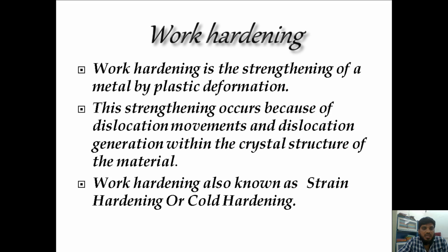I can tell you an example. If you are stretching a material and you leave the material after stretching, you have given a plastic deformation to the material. The important thing is that it is not applicable to elastic deformation, it is applicable to plastic deformation. If you take a rod and stretch it, once it has undergone plastic deformation, the material is already enlarged. So if you want to compress the material again, you first have to reduce whatever enlargement you have given.